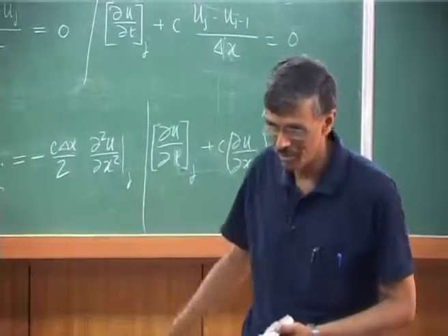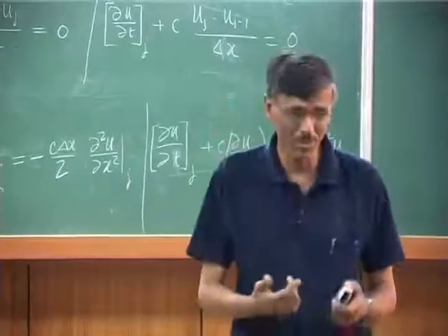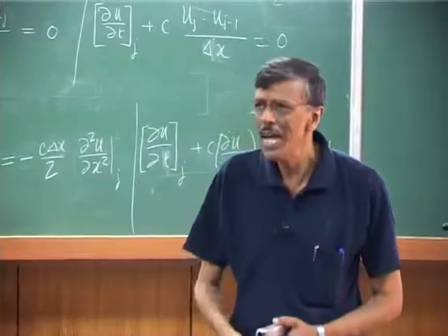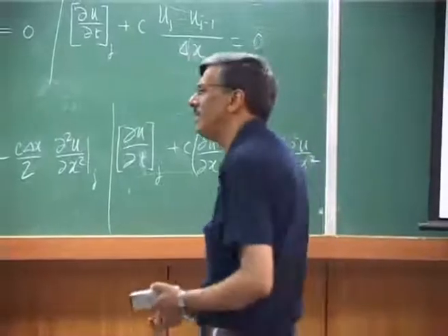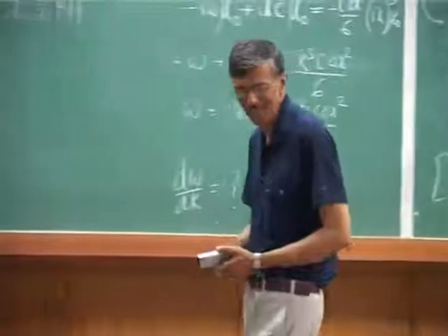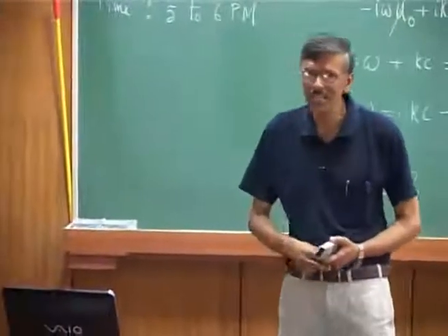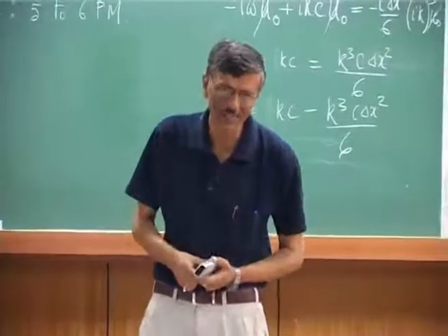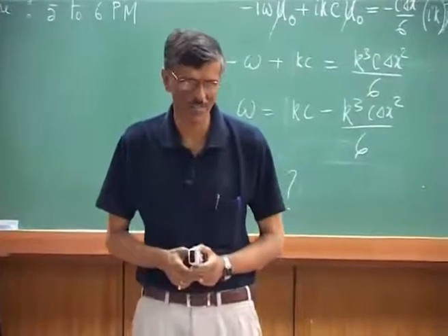How do I add dissipation? We have seen that first order upwinding is equivalent to adding a second derivative term. In many physical problems, you will find that the governing equation already has a second derivative term. Then is it safe to add a second derivative term for numerical stabilization?